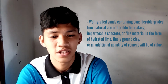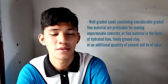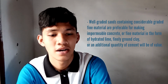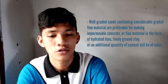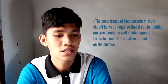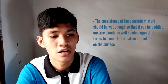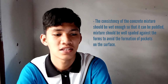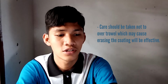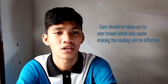Well-graded sands containing considerable graded fine material are preferable for making impermeable concrete, or fine material in the form of hydrated lime, finely ground clay, or an additional quantity of cement will be of value. The consistency of the concrete mixture should be wet enough so that it can be puddled. Mixture should be well spaded against the forms to avoid the formation of pockets on the surface. Care should be taken not to over-trowel.